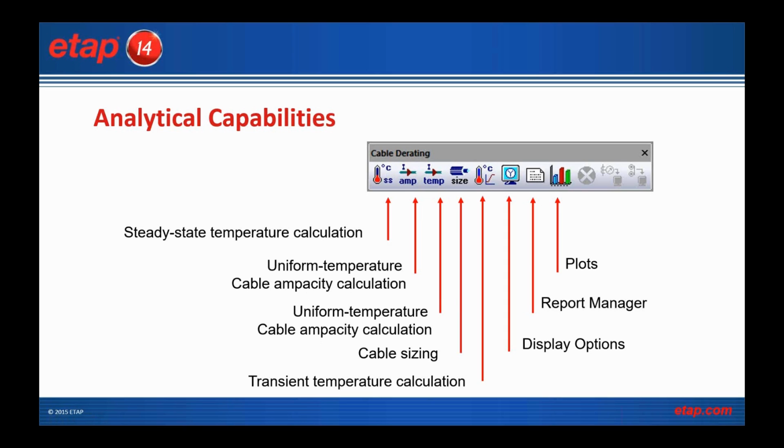It bumps up the profile over the base value and then tells you how much more capacity does the raceway have if you continue putting the similar type of current uniformly through the raceway. There's a uniform temperature calc that basically tells you what is the maximum capacity of that raceway, assuming that all the conductors reach their temperature limit.